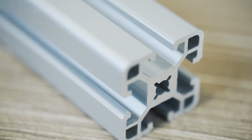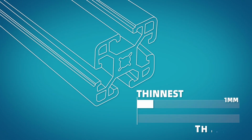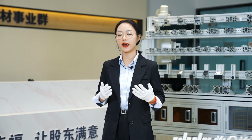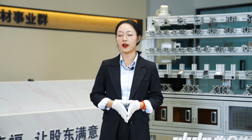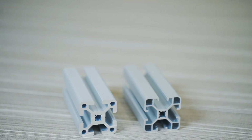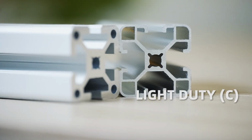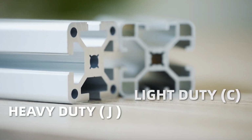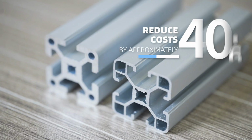For standard profiles, the thinnest wall can be 1 mm, while the thickest can be 6 mm. The thicker the wall, the heavier the weight per meter, and the higher the cost. For example, if there is no load-bearing requirement, selecting the 14 series specification with the suffix C can reduce cost by approximately 14% compared to the same series with the suffix J.